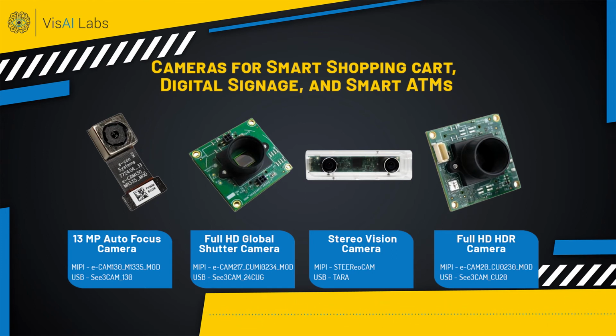So if you are just looking for facial recognition, not going to do the spoof detection, then probably a 2D camera will be fine. But if you need to do spoof detection, like presentation attack detection, then you might need a 3D camera, which will give you both a 2D image and also depth information to check whether it is actually a real person or a photo or a video.